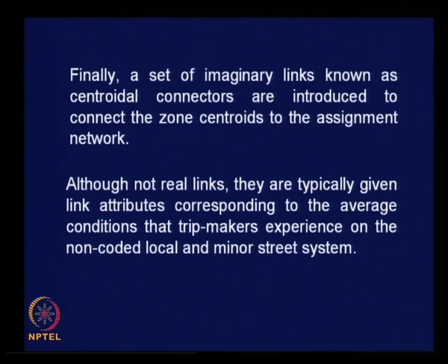Although not real links, they are typically given link attributes corresponding to the average conditions that trip makers experience on the non-coded local and minor street systems. There are several local minor streets which feed traffic onto the main roads. These imaginary links represent the traffic flow on all the minor roads within a traffic zone.